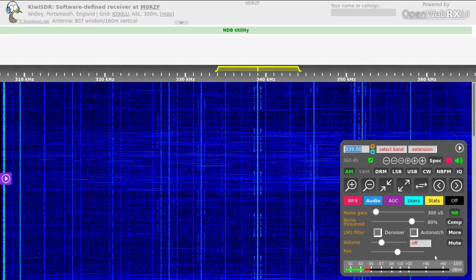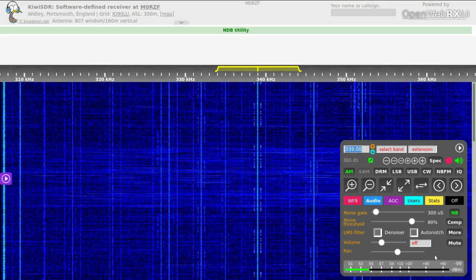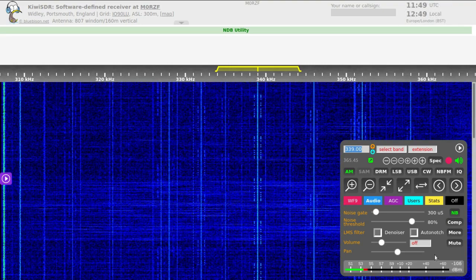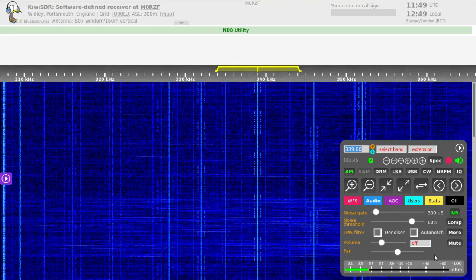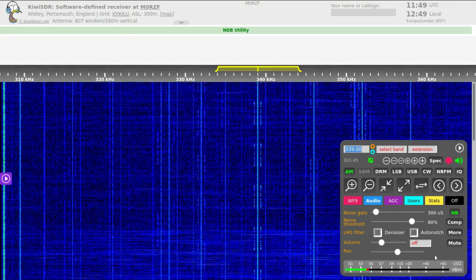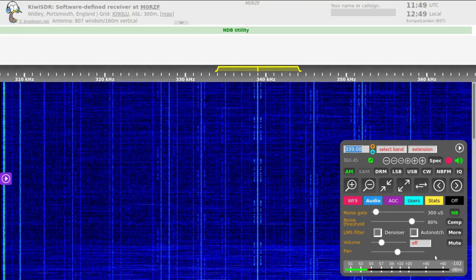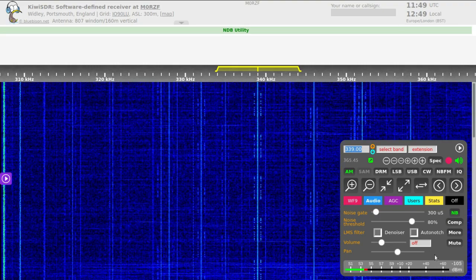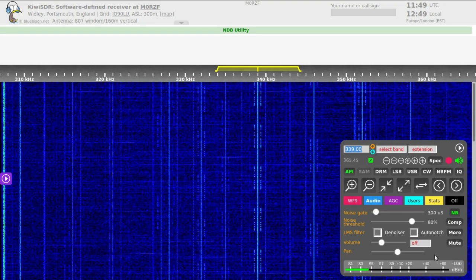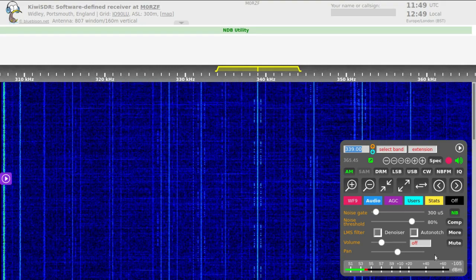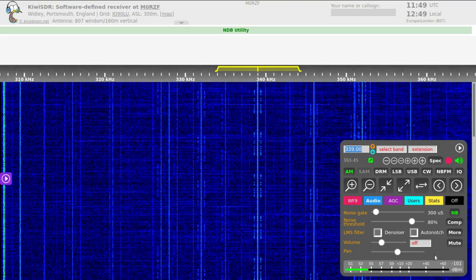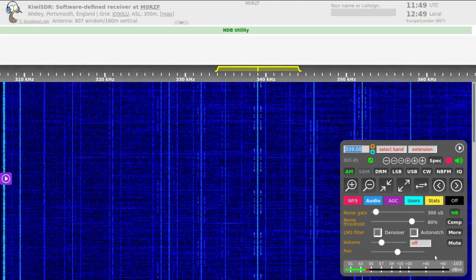There is other weaker pulse interference on the frequency. That's due to other sources which are emitting the pulses with a different amplitude, phase, and duration. An 80% threshold in 300 microseconds seems to take care of this pulse very well. Judging from the pitch of the buzzing, I would guess that it is from the power lines around there.